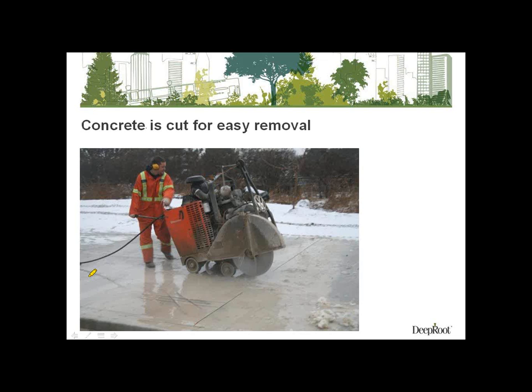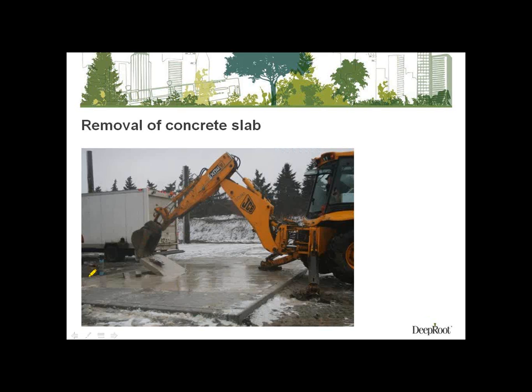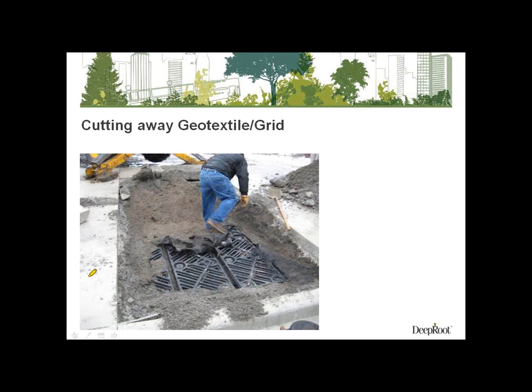Okay, once we got enough water bubbling through to make a big mess, we decided it was time to start the repair. First thing was to saw the concrete on top into panels that could be easily removed by an excavator. Next, again, expose the aggregate on top down to the geotextile fabric, and then cut the geotextile fabric out of the way.